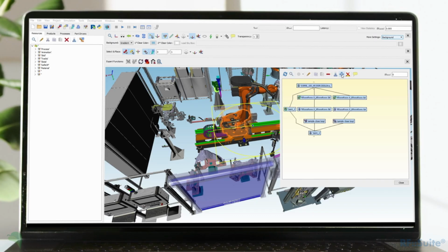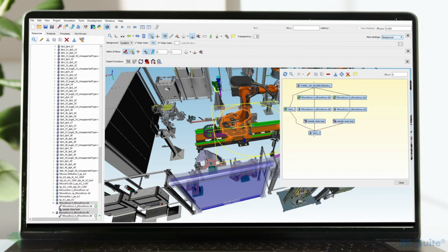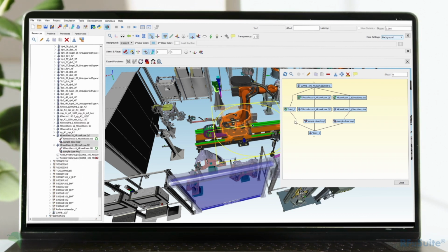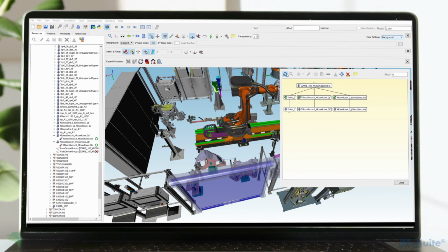We have added two new functions to the Kinematic Graph to help troubleshooting of common issues. With a click on Select All Loops, you can now easily check and display closed kinematics inside the project to correct them. If an element is not connected kinematically to the static body, you can neither move it nor use it in any function. To check for incorrectly connected content, you can now use the Select All Bodies and Joint Without Connection to a Static Body button in the Kin Graph to display them in a fast and easy way.